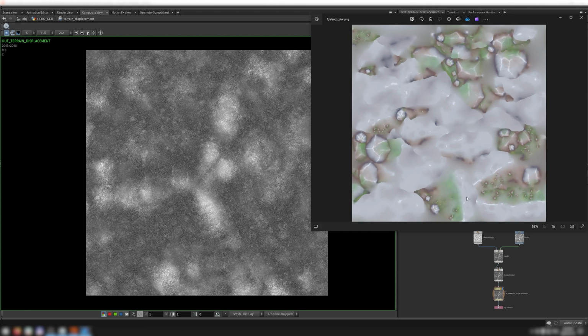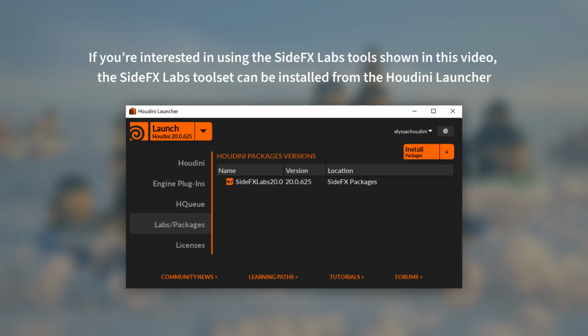Note that unlike the base color and roughness texture, which respect the mesh's UVs, this displacement texture is just a random noise image. But because the displacement I apply is so small, you don't really see any seams in the final render. So even though this isn't a perfect setup, it worked well enough for my purposes. And that's it for the terrain shading.